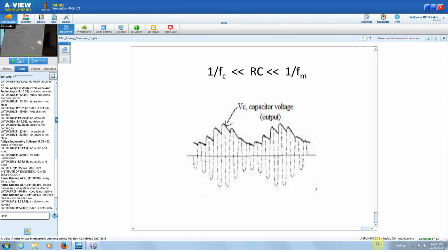And we'll assume that the source we are giving has very minimum resistance. Source resistance RS is very small, or ideally it is going to be 0. RS we are saying very small, so that your envelope detector will not load any of your source circuit. So we want the source to have very low source resistance, RS. That's what we are assuming for our envelope detector.